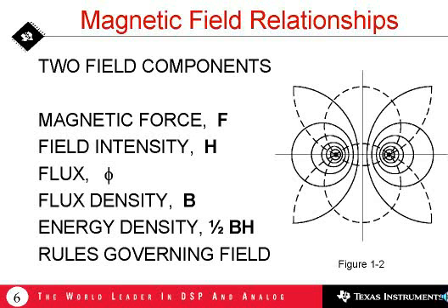There are 6 or 7 simple basic rules that govern the magnetic field and the way that it arranges itself around these conductors. The most important basic rule is the law of conservation of energy. This dictates that the field pattern will set itself up in a manner to minimize the stored energy. If our purpose is to minimize inductance, this is equivalent to saying we want to minimize the stored energy, and this can be accomplished if we understand the rules of behavior and structure the situation so that the law of conservation of energy can produce the desired result.